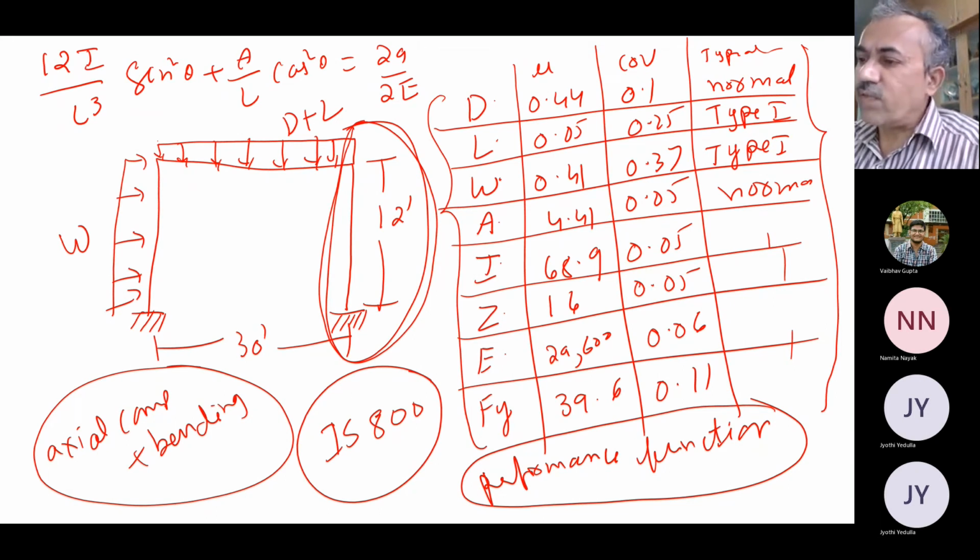So you find out the stiffness matrix of this framed structure using the frame element, and then you write one more subroutine to find all the derivatives, and then you do it in a loop, with the Hasofer-Lind reliability program, that same program you can use. But here one more important thing is, which procedure will you use for reliability calculations? You can use Hasofer-Lind, or what is that you have to do? Something extra you have to try. What is that?